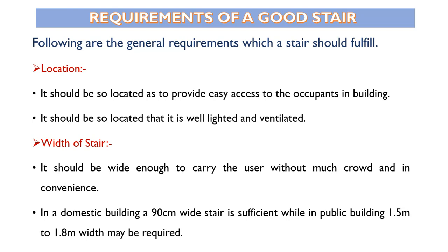So where should it be located? It should be so located as to provide easy access to the occupants in the building. It should be so located that it is well lighted and ventilated. So the location should be such that it is easily accessible, properly lighted and properly ventilated. As far as possible, the stair should be located centrally so that each and every occupant gets access to escape from any sort of disaster, and can use it comfortably.